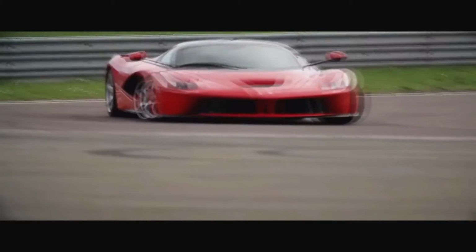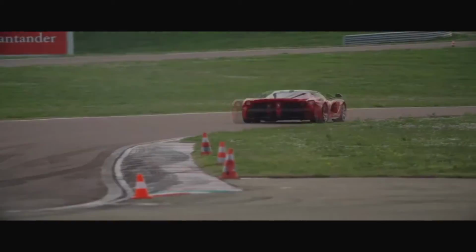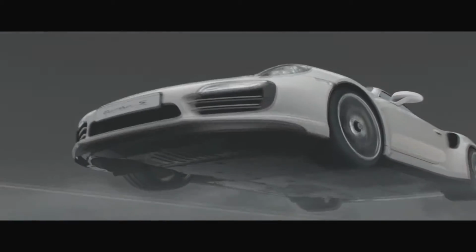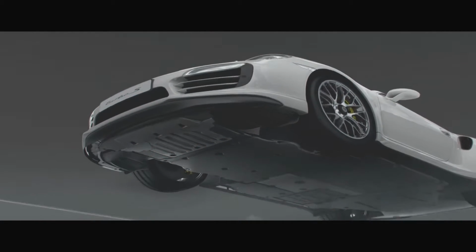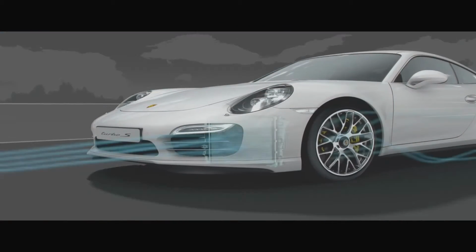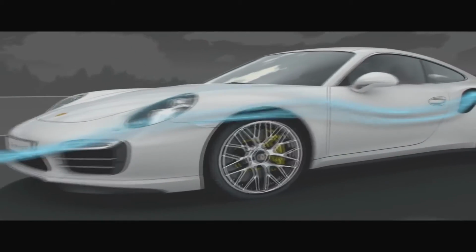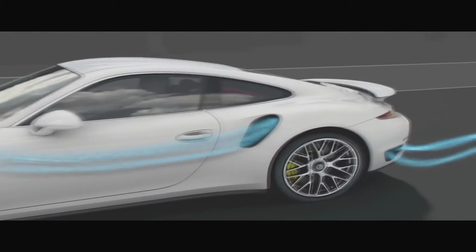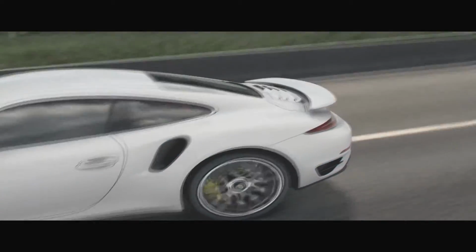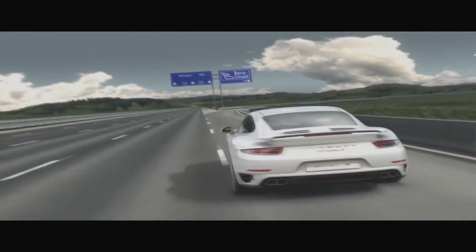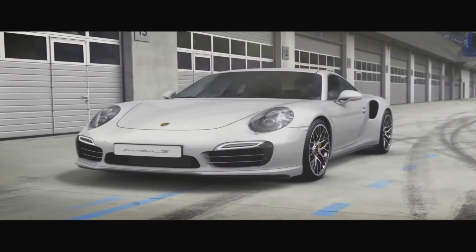In a lot of the stuff we covered, like spoilers and vortex generators, those things are set to have a sweet spot and be most performance friendly at a specific speed. With active aerodynamics, the aim is to be able to adjust the angle of attack and height of the spoilers, splitters, and even canards. Anything really that comes in contact with the air is allowed to move and change its angle and position to create the lowest possible drag coefficient for the vehicle at just about every single speed above a reasonably high speed.